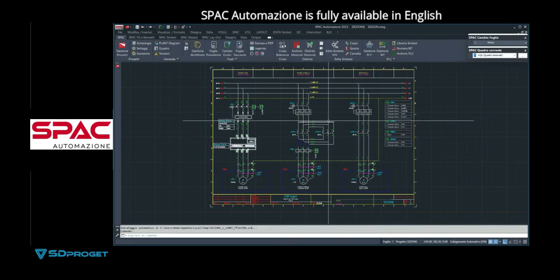So you had to go into the insert blocks command and say, no, I want to redefine it. I want to take the block as it is now. And erase and redefine. Then update the old blocks to the new block. So if I had 100 blocks, by doing one command, they were all updated.